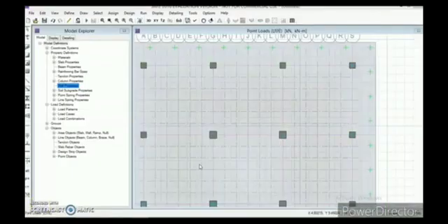In the meantime I have assigned the remaining dead loads and live loads to all the 16 columns. So now the assigning part is done. We have assigned the loads as well as the concrete properties initially, and before assigning the load properties, we have also assigned the steel properties to the column. We have already assigned the soil properties to the footing as well. So now everything is done. We just need to check our analysis.